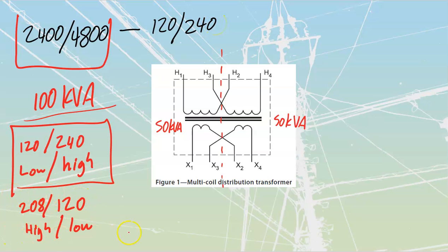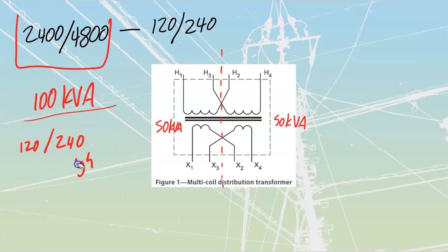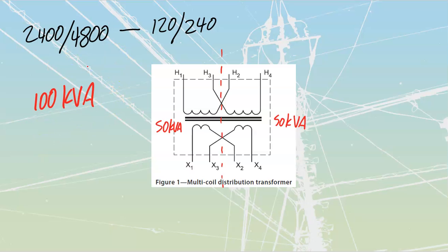Okay? Anytime that you see the high and then the low, if it was written intentionally, it's going to be indicative of a three-phase type of system. It's widely misused, though, both of these ones. People just kind of throw numbers out there, like 120/240 or 240/120, etc. Inside of the book, though, we are going to try to stick to proper notation.